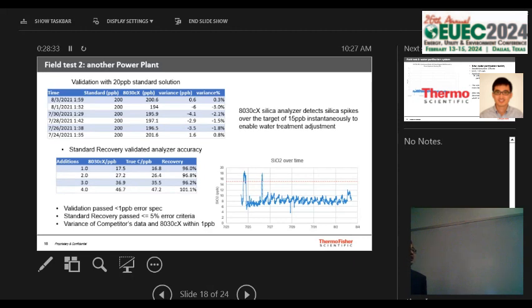And occasionally they also get one below 15. That's ideal, because 20 they definitely don't want to exceed, but 15 gives them a good buffer. So every time they exceed, they can see that from the analyzers. They can take proper action right away, say divert water, recycle, or try to improve their operation. Maybe their RO or their ion exchange resin needs to be swapped. So it's a good indication for them to look at those things.